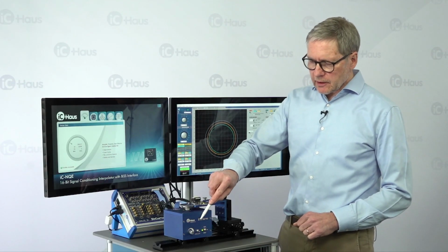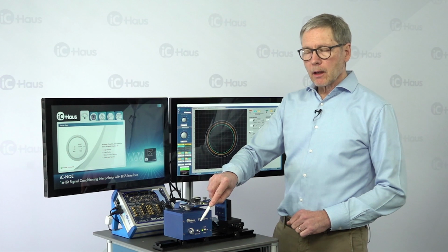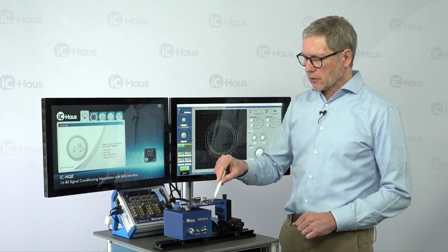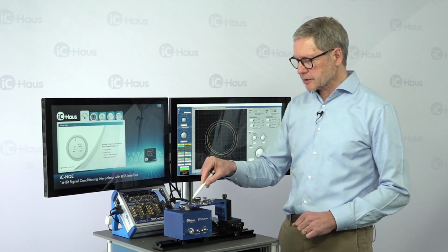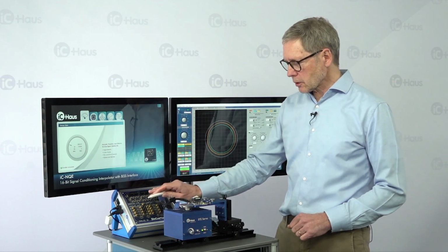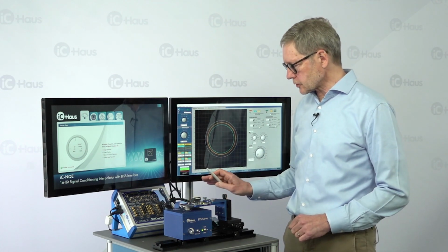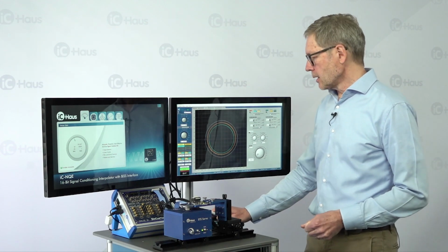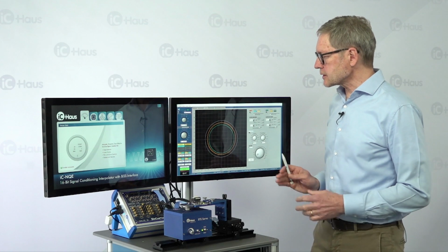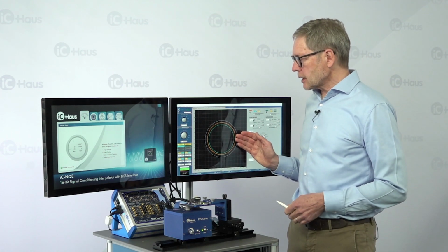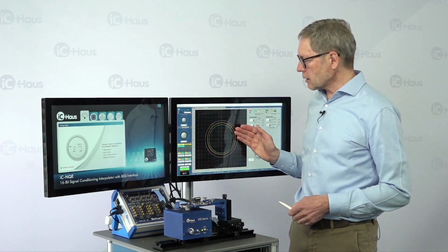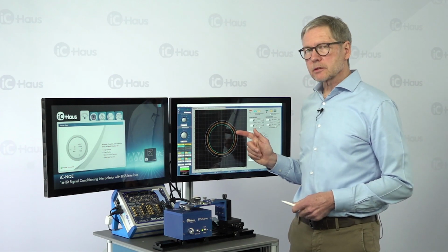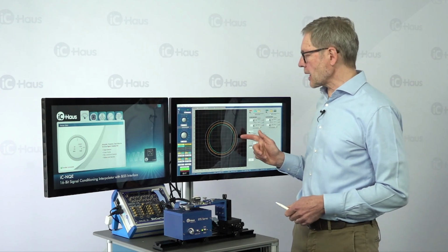As explained, that's our drive with the reference encoder. Here we have the sensor PCB, the inductive sensor. The evaluation is on this PCB, passing on the signals to the synthesizer and besides on to the BiSS adapter. That's the new one, MB8. You can also use the MB5U. Now, initially, when we look at the Lissajous figure, we can see that there's the input signal, the orange one, and the output signal, the blue one. Our target signal, the 1 volt peak signal, is the white target circle.